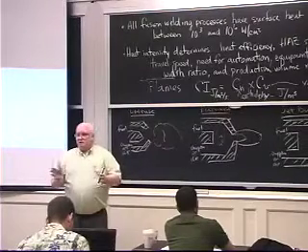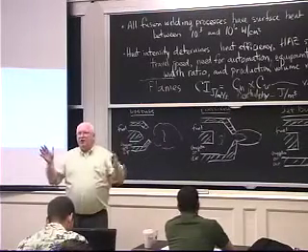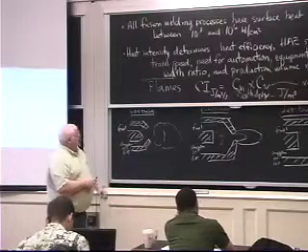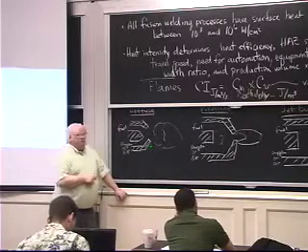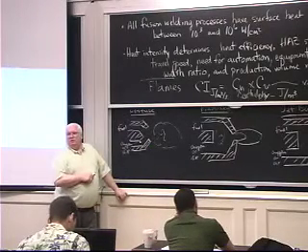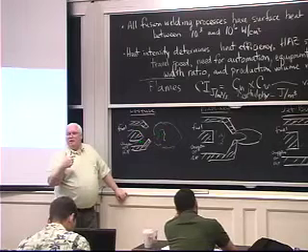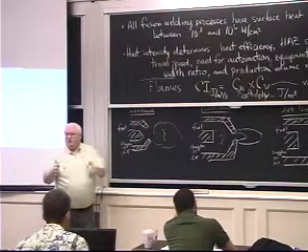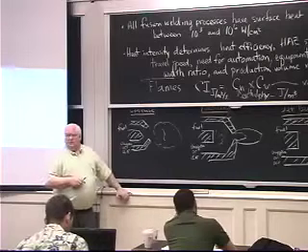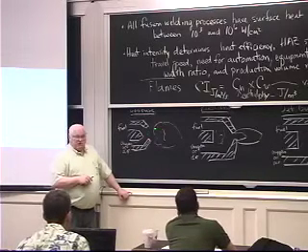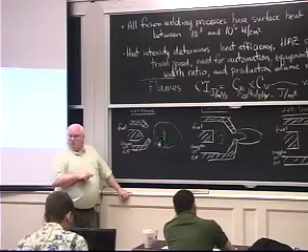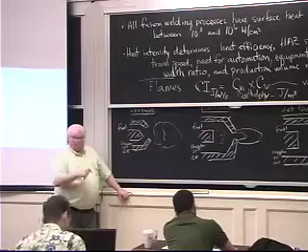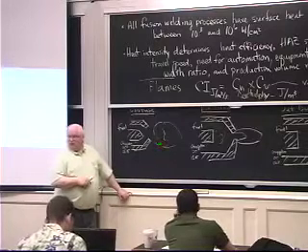It's not pre-mixed, and the burning velocity is relatively low because you don't have optimum mixtures of fuel and air. You have whatever mixture will burn and whatever statistically comes together with the right burning velocity, and you already have pre-ignition from something. This flame has been going on for a while. And so that's a diffuse flame.